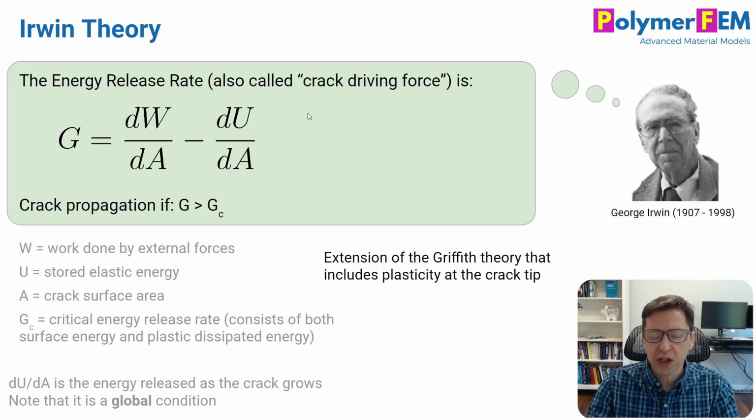And the fracture condition simply is that if the energy release rate exceeds a critical value, Gc, then fracture will occur. So this is an extension that actually allows for some plasticity really close to the crack tip, or any dissipative mechanism like that, as long as you have a field outside that region where the response is driven by linear elasticity. So this is kind of an interesting idea that he came up with. This is also a similar foundation to elastic-plastic fracture mechanics that I will talk about in a different video.